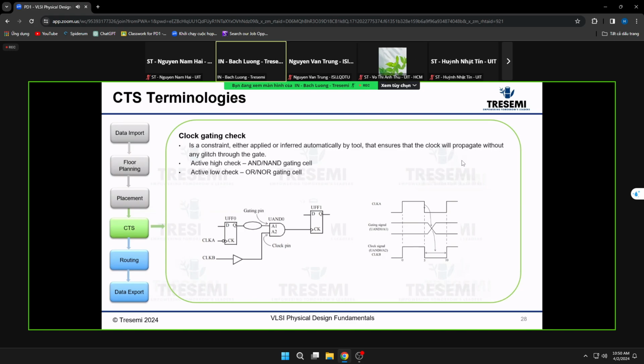So saving power is important, right? Because if the chip is power hungry, it can also burn up your die, and you need a heat sink and so on, different packages, so that impacts a lot of things. So saving power and keeping your chip cool is far more important than some of the added area and things like that I mentioned.